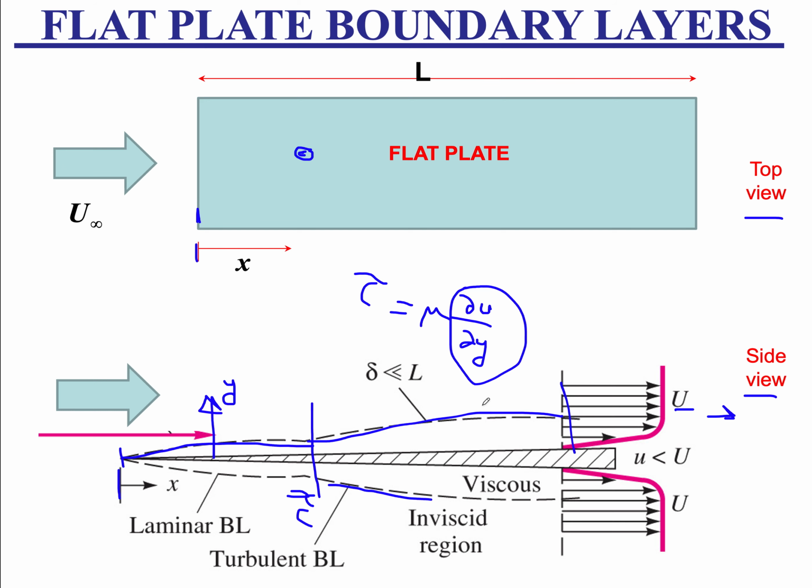Outside this region, the level of strain rate du/dy is going to be very small, that this number is 0. So when you multiply 0 by viscosity, it really annuls the effect of viscosity. That's why we say it's an inviscid region. Still, the air has its viscosity, but the effect of viscosity just doesn't show up because there is no strain rate. So that's what we mean by inviscid region and viscous region. Inside the boundary layer, it's a viscous region. Outside the boundary layer, it's inviscid. The viscosity is not acting in there. It's just sleepy. It's dormant.